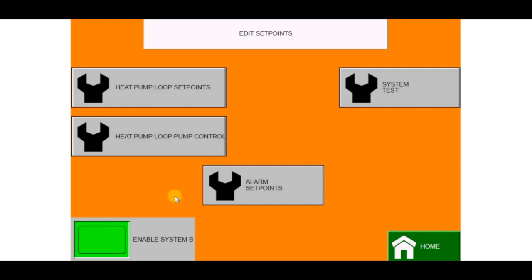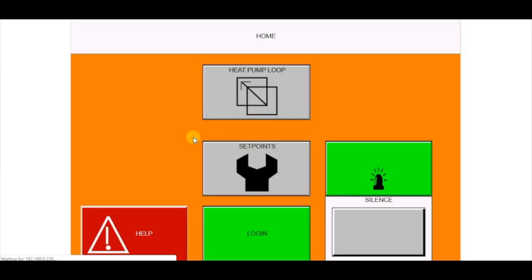On the Flex panel, there's a PLC on the door, and the PLC has a couple different soft keys. One of them is the system button, and you can use the system button to change the time. If you're data logging, you'll want the timestamp to be accurate, but other than that, the system key is not something that needs to be accessed very often and actually contains some sensitive communication configuration settings that need not be edited. So we have this enable and disable button to keep those menus from the hands of unauthorized individuals.